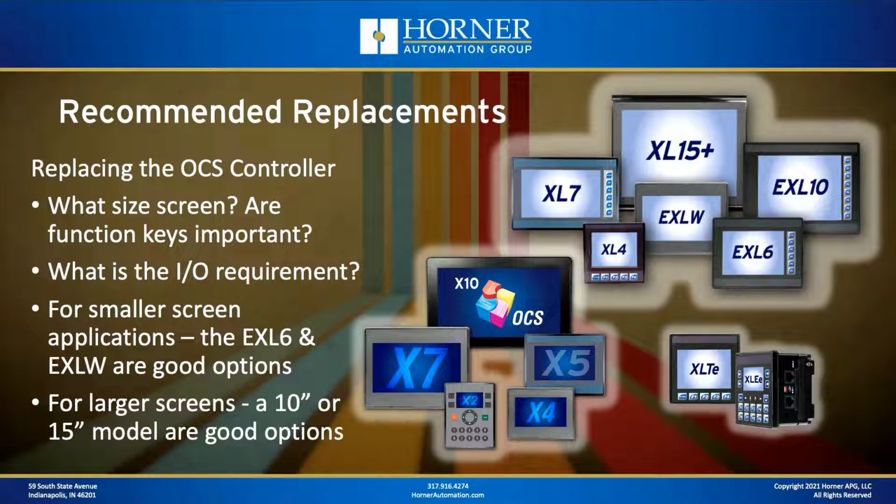Well, of course, what size is the screen you're replacing? Were the function keys used in the application? If they were and you want to maintain that, then you'll probably need to look at a unit that maintains function keys. What is the I/O requirement? Whether a unit is graphical based or a text-based OCS, the I/O requirement is an important factor that you need to take a look at. The Micro series and the XL series have very different I/O capabilities, at least in terms of what's built in.